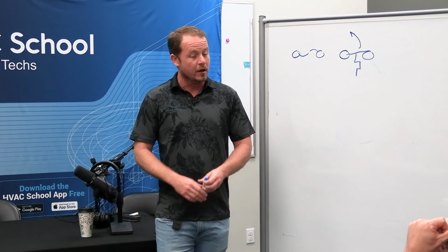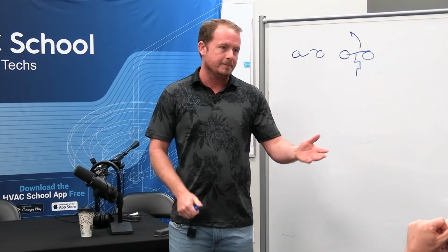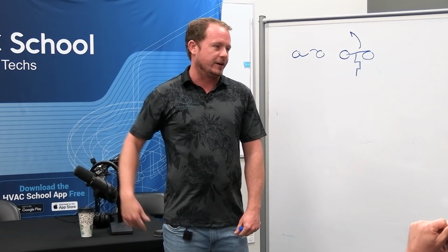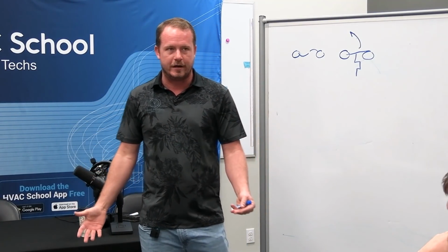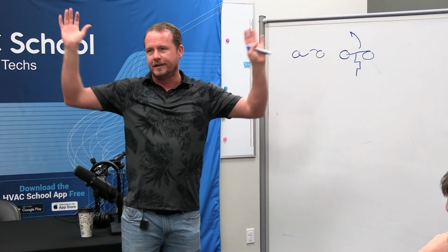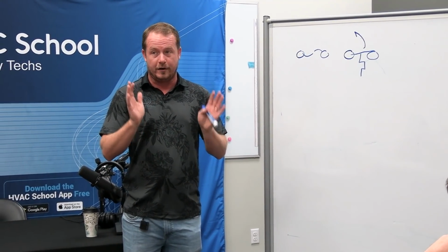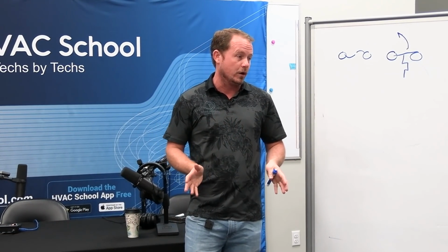The customer doesn't want you saying, all right, I'll come back 6 hours later. It's one thing if you're working on a facility like a CubeSmart where you're going through maintenances, you find one overheating, well, then just shut it off and come back later. Right? That would be fine. Or if you're a facilities engineer and you've got a ton of units and it's not affecting the customer. But if you're there on a service call where you drove there and it's a residential customer, you need to get it cooled off. And the right way to do it is to run some water over it.